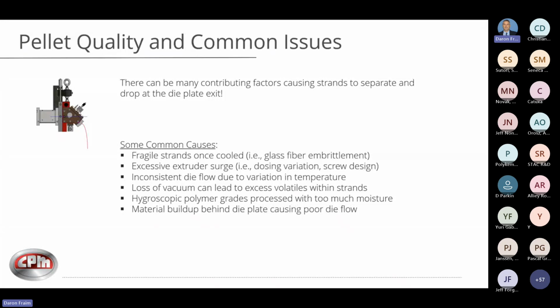Again, if you're dealing with what I consider excessive extruder surge, this can be a constant issue that you're always seeing. Again, that tug of war match with the pelletizer. You can see the pulling. It just literally separates the strands.